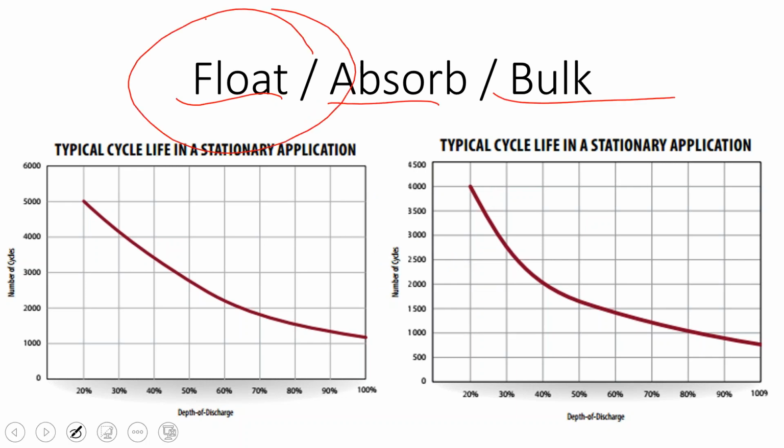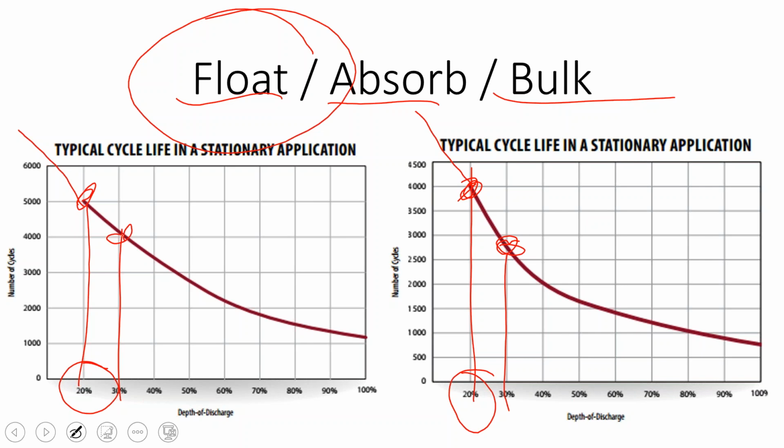And so the float phase occurs at the top of the battery. You notice on this chart, it doesn't go up to 0%. It says it keeps it at 20%. Depth of discharge is where the graph kind of starts. And on lead acid batteries, the rule of thumb is don't design to more than a 30% depth of discharge. That's the general industry rule.